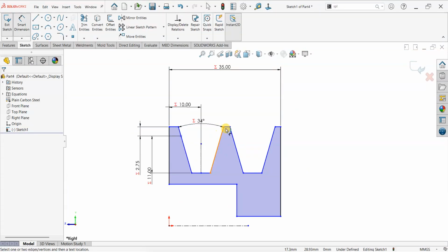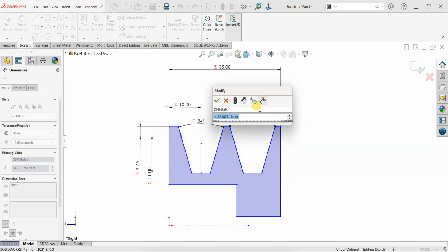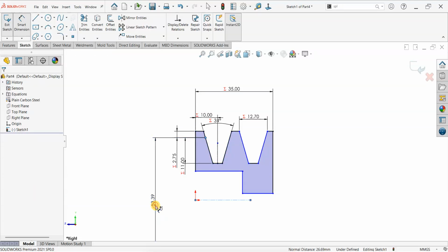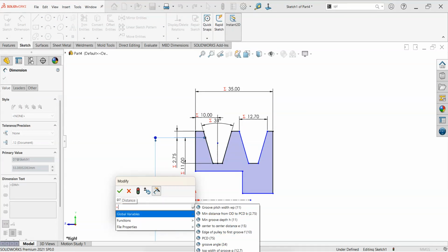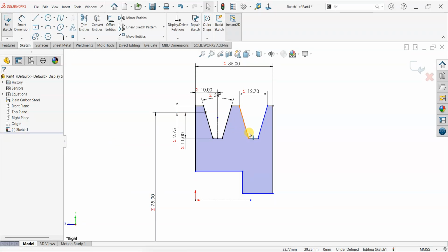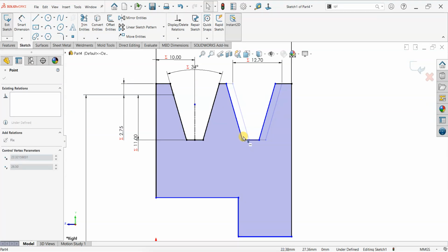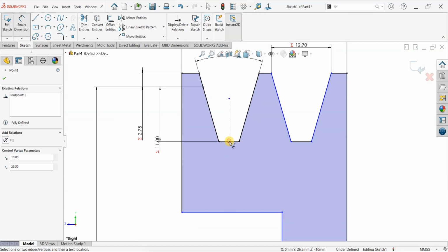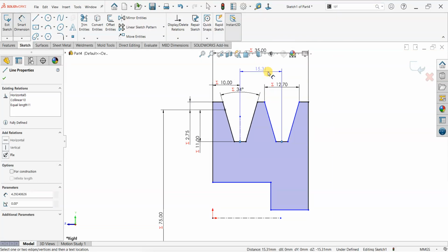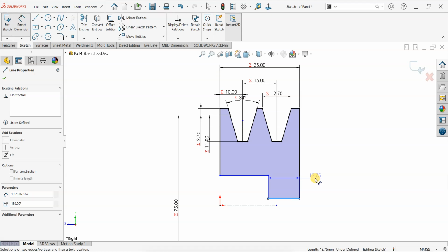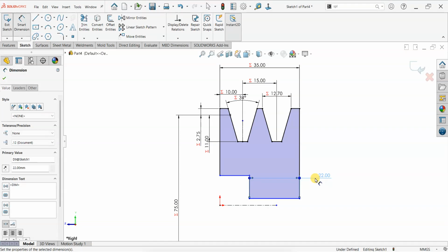Now we can define the top width of the groove, which is top width of groove. Hit enter. Now we need to define pitch circle diameter, PCD. Okay. Hit escape key. Try to move the sketch, and as you see, we click on this line and this line, which is a center to center distance, and this line give dimension like 22.